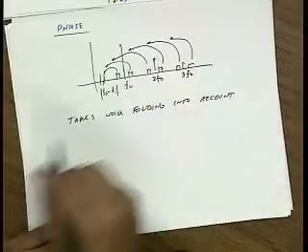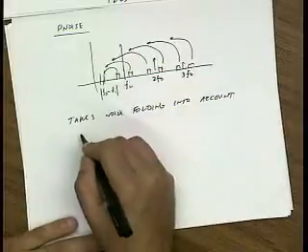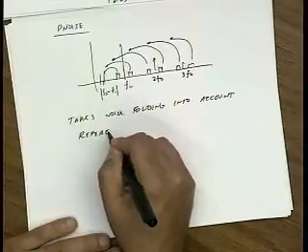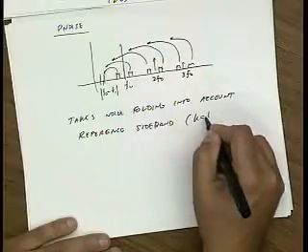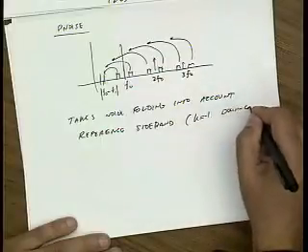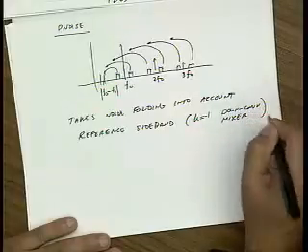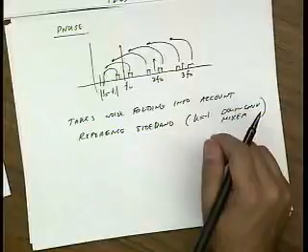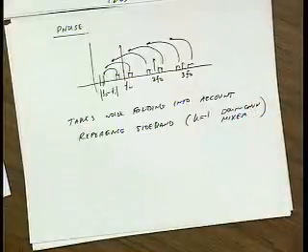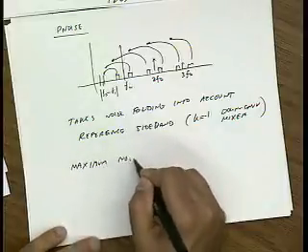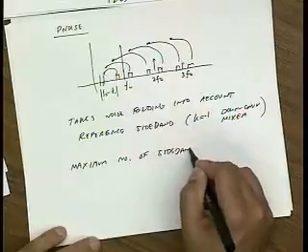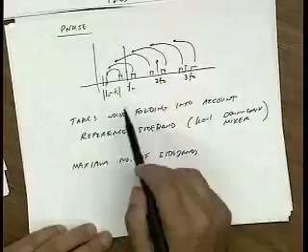And in order to make it work correctly, you have to specify, again, the sideband. For instance, K equal to -1 for a down conversion mixer. And you have to specify the number of harmonics. I think it calls it, is it the maximum number of sidebands or the number of harmonics? Maximum number of sidebands? Yeah. So you also have to specify the maximum number of sidebands, because obviously it can't do an infinite number. It would take an infinite amount of time.